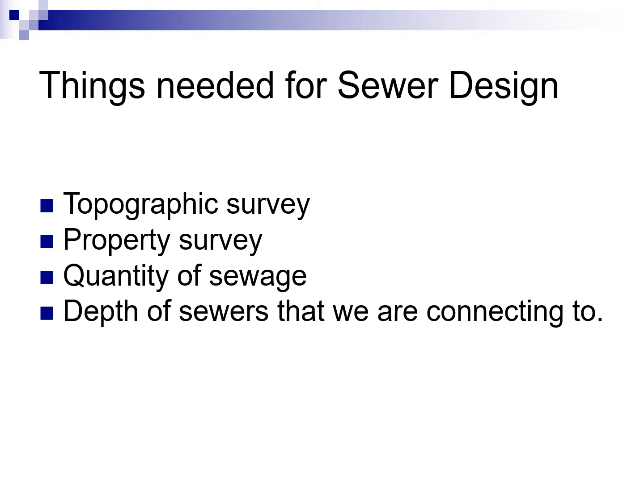In a lot of areas, like in my personal house, I have sewers, but the sewage service line actually is about 3 feet up from the basement wall. So it would mean that I really cannot provide basement service here. If I wanted to install a sewer in a bathroom in my basement, I would have to then have a pump to get it up to the service line.